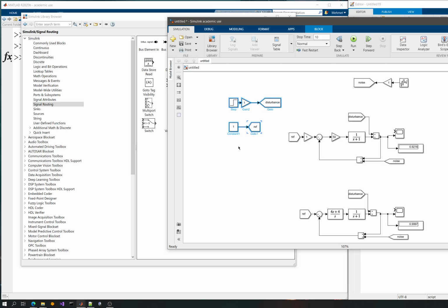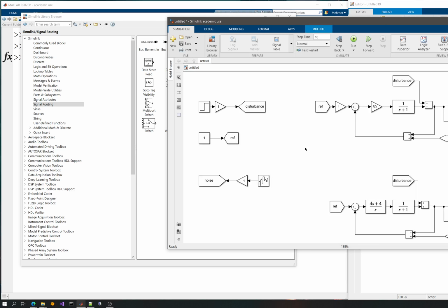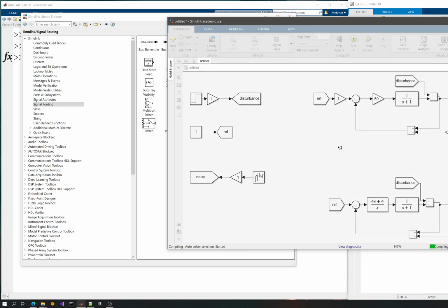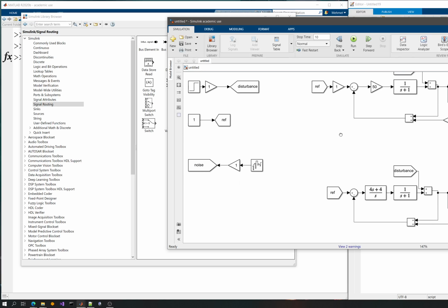You can also arrange them so that they are on the left, and also drag this down here. And if you hit space, you have a nice tidied up version of the same simulation, because at some point in Simulink you might have some issues keeping track of the connections. That can be a pain, but using these tags it's possible to solve it, and you can see that you have basically the same thing.